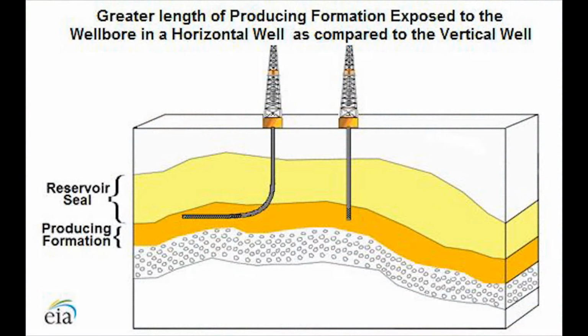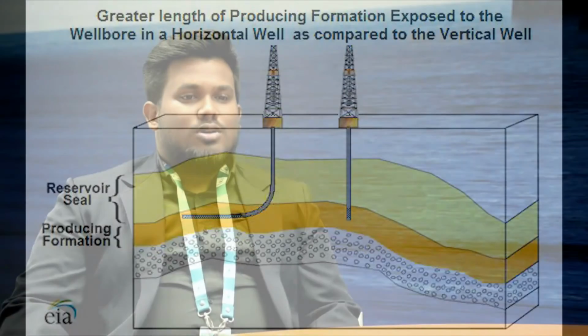Drilling a horizontal well has its own advantages, such as water and gas coning can be reduced due to the reduction in drawdown in a given reservoir. Also, production rate can be increased due to the larger exposed area of wellbore to the basin. Moreover, pressure drop and fluid velocities around the wellbore can be reduced, thus leading to the reduction in sand production. Lastly, overall reserves production can be increased due to the larger and more efficient drainage pattern.